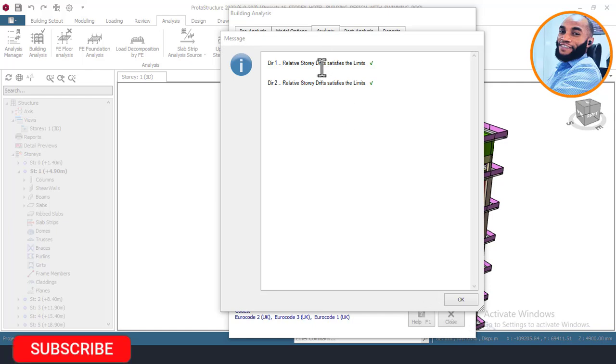Okay, so again, here right now you can see that our relative structural drift on both directions is satisfied and it's okay. So make sure that your drift is always okay when you're done with your building analysis. Once it's not okay, don't just accept it. Make sure this good is ticked. This good that is ticked here means that it is okay. So you can see that on this 16-story building, our model and also our design is perfectly okay.